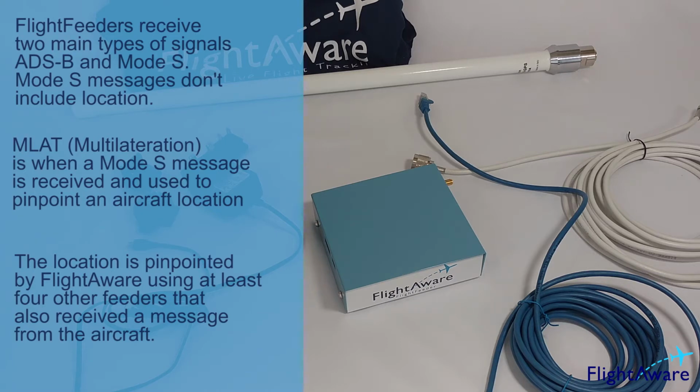Mode S messages, on the other hand, don't include location, so if your station sends a message to FlightAware about a particular aircraft, FlightAware will look for other stations nearby that also sent a message about that aircraft. And if 4 or more stations send a message to FlightAware, the location of that aircraft can be pinpointed. This is called multilateration, more commonly referred to as MLAT.